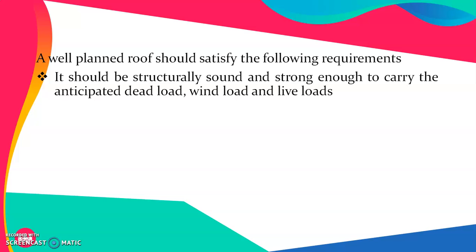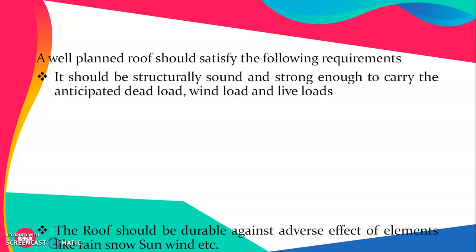If a roof is flat in nature and it has got an access, then users generally use the roof as a terrace. So that particular roof should be structurally sound to support all these kinds of live loading. In case of sloped roof or curved roof, generally such kind of access is not there. But still that load might be there, particularly in case of repair work. So that roof should be strong enough to bear all such loading.